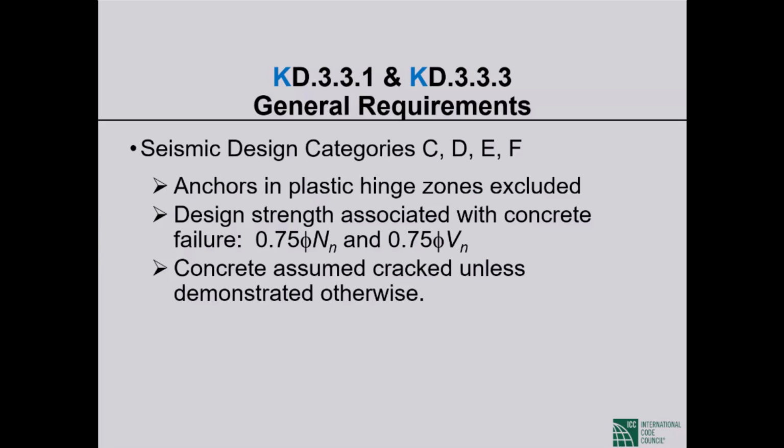Then, very importantly, concrete is assumed cracked unless you are able to demonstrate that concrete is going to remain uncracked under service level load. And that demonstration is not simple. Okay, so this is very important. Concrete is assumed cracked under seismic applications unless you are able to demonstrate otherwise.